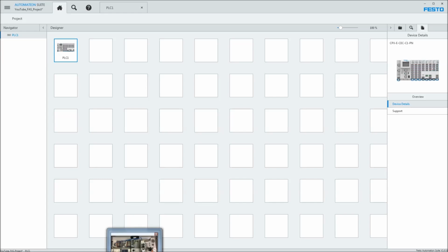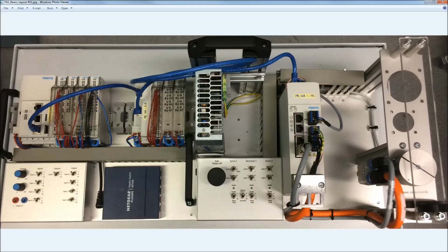So hardware that I'm dealing with here. So I have borrowed some equipment from Festo, and I have the PLC over here on the left-hand side. This PLC has got 2 Ethernet ports here, and then it has an EtherCAT master. And then on the left-hand side, you can't see over here, there's some Profinet, which I'm not going to talk about. EtherCAT leaves the EtherCAT master, goes to the input of the CPX-E-EC, so the EtherCAT module, and then leaves this port, goes to CMMT.